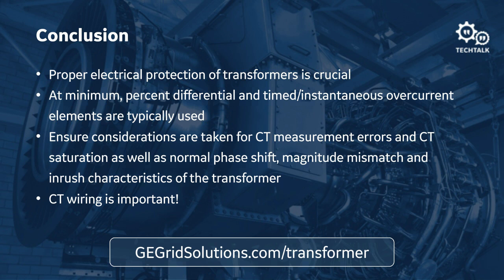It's basically a spreadsheet that has the algorithm built into it, where you can enter your winding and CT info, your settings, and the test currents that you're using. Then it'll plot the dual slope characteristic for you. And with your test currents, it'll show where you lie on the characteristic, whether it's going to cause a trip or no trip. If you'd like more info on where to get that tool or on the calculations, let us know.